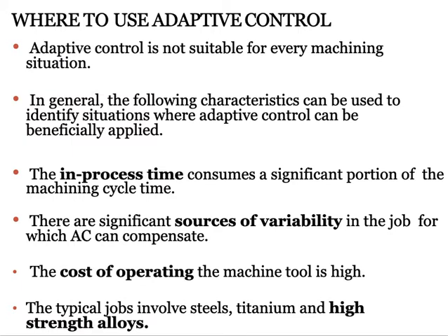Here, the NC or CNC controls sequences of tool positions or the continuous tool path during machining. There is a possibility of spindle direction changes, an increase in cutting temperature, tool air gaps, material property variations, or machine tool vibration. These process parameters waste productive time. The most promising means of reducing the unproductive time is the use of adaptive control.